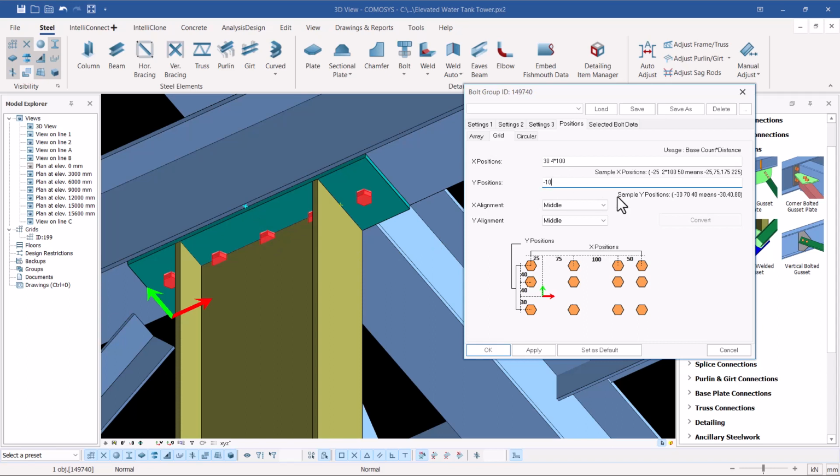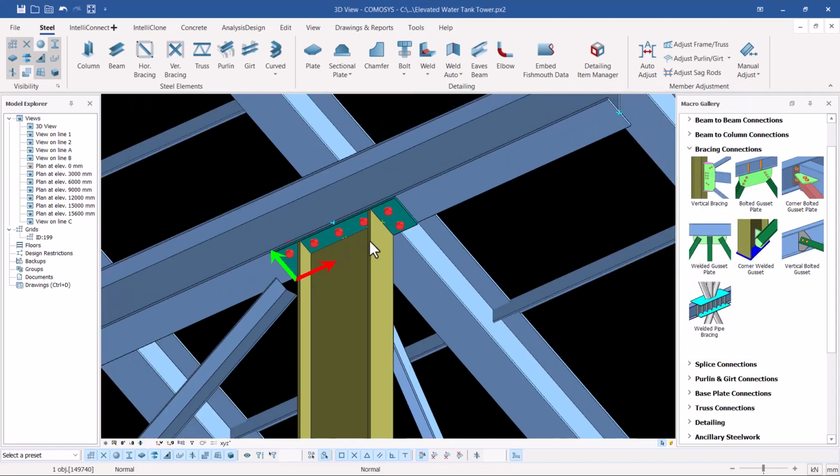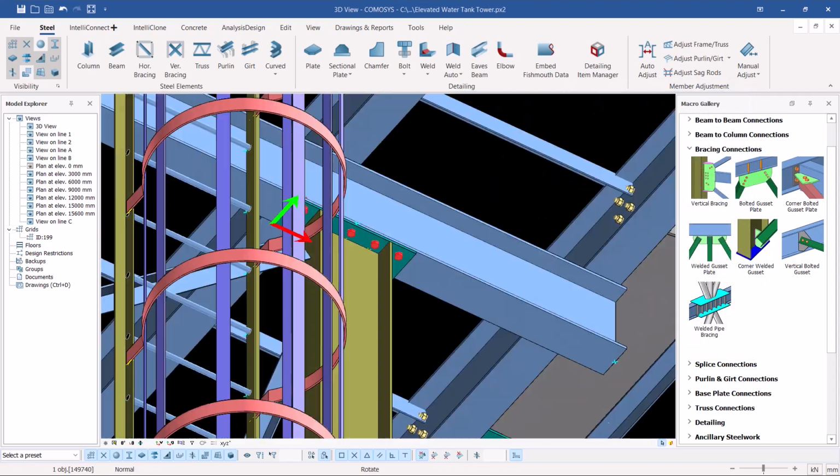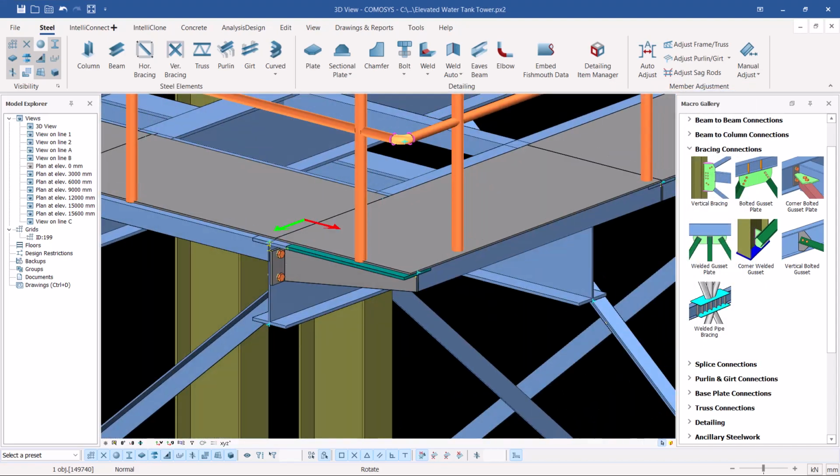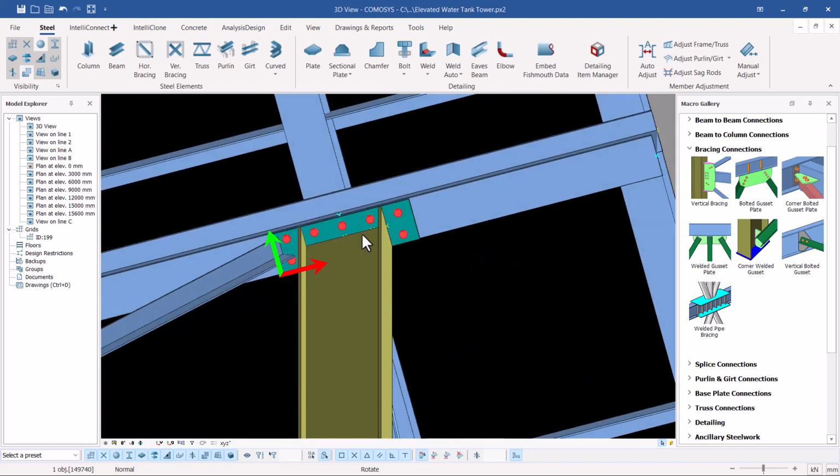We'll come here and feed in, maybe we need 80 right there, and if you click apply, we'll get an offset of 80 relative to our absolute point that we had created previously. So if I click OK and turn that round like that, we'll find this already bolted perfectly.